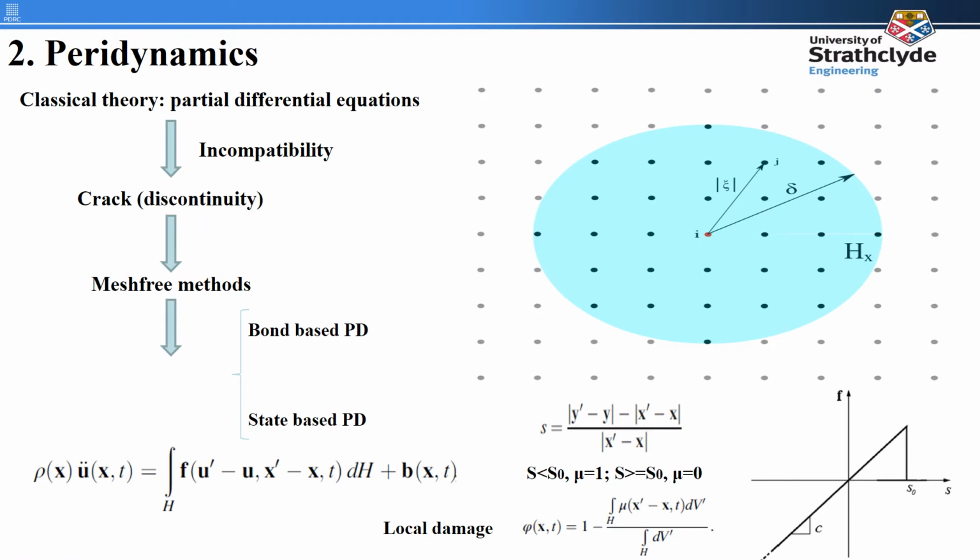In order to research the fracture behavior related to porosity, we prefer to use peridynamic theory. The traditional classical theory based on partial differential equations is not easy or convenient for dealing with discontinuous problems. Although many mesh-free methods have been developed to solve this problem, usually they are still quite complex. Peridynamics is improved from these mesh-free methods and was created by Dr. Silling in 2001. The governing equation of peridynamics is an integral equation, which allows us to solve fracture problems easily.